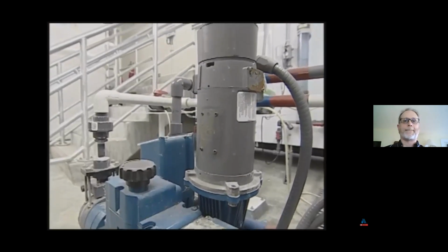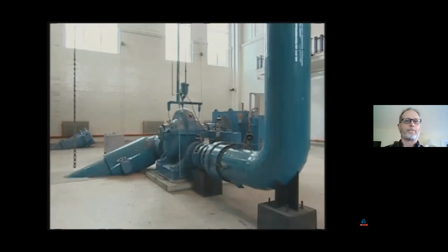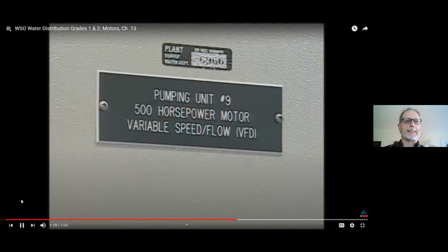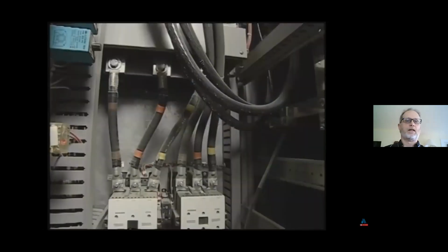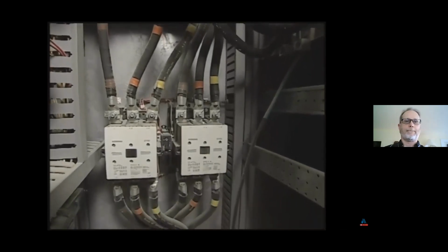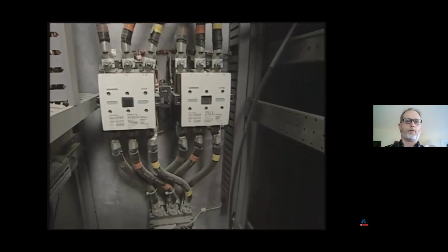Small motors are usually started by directly connecting line voltage to the motor. Large motors are typically started and stopped using a reduced voltage motor starter. A motor starter includes a main disconnect switch, fuses or a circuit breaker, motor protection for temperature, unbalanced current and other parameters, and provisions for remote operation.